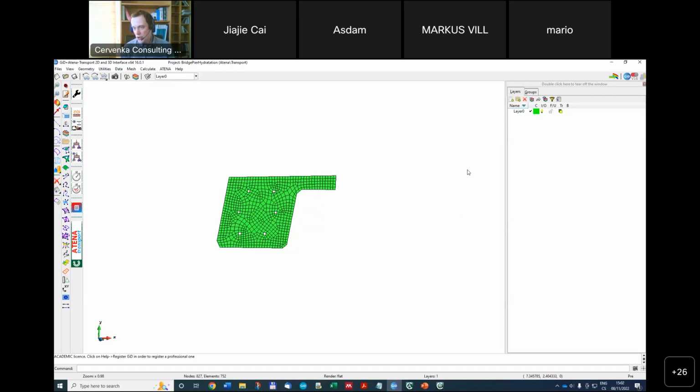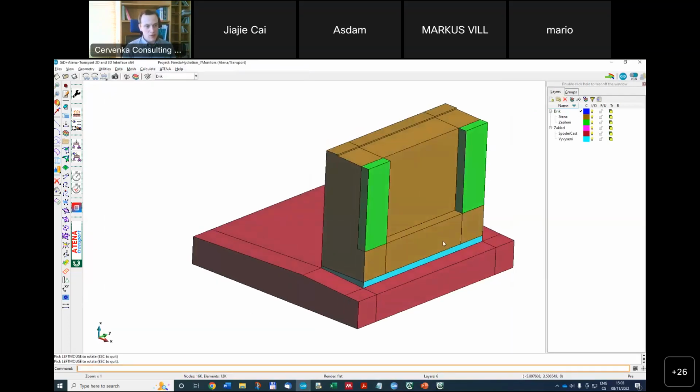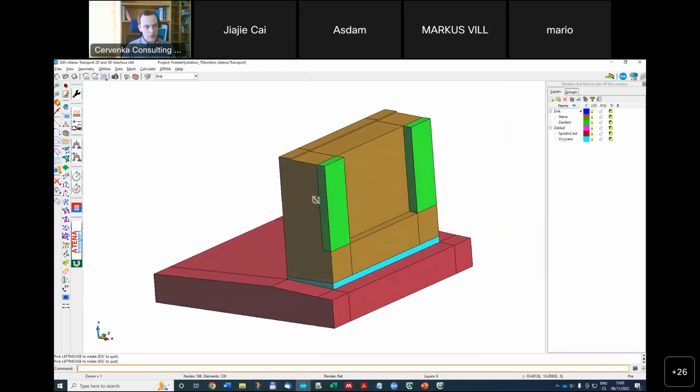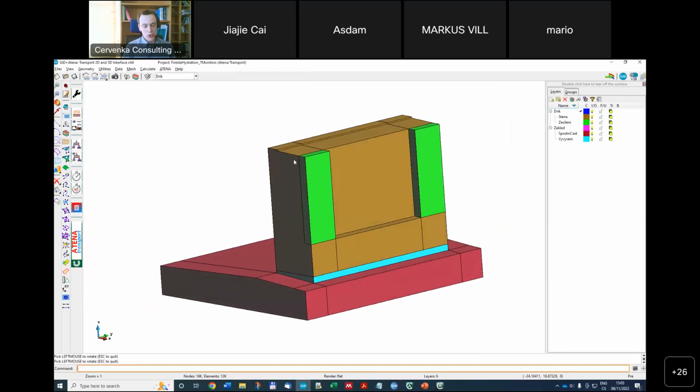Another question is: should we model the volume of insulation in a temperature problem, or in order to set its heat capacity or density? Yeah, as I mentioned, there are two options generally. One, if you have the insulation, you directly simulate it. Let me assume this model. It would mean that I would duplicate this surface and create an extra volume on the side, which would represent the layer of thermal insulation, and then I can have this directly in the model.